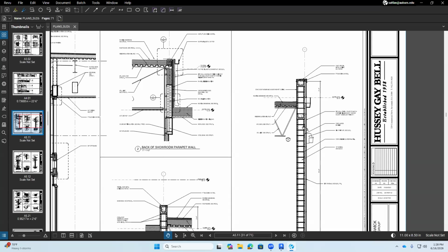If I'm going to have an opening in here, and whoever did this wrong, look at the crack. Look at the crack over there for the drywall. What did that guy do? He cut the drywall up here. You really need to cut it somewhere over here so that that crack doesn't appear. That whole thing is because of the way they cut the drywall.